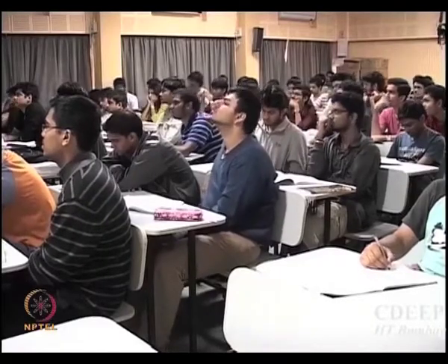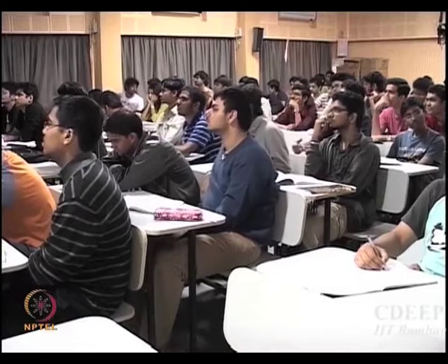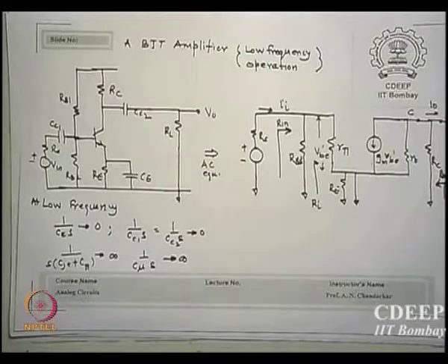Since, as I say, there should be a little pedagogy. Equivalent common emitter amplifier. Okay, the amplifier was shown last time also. What things are left out in all equivalent circuits? Capacitances. Why did I leave them out? I say I am working at low frequencies and all of them are open or short as per the requirements. Okay, I am not considering them.